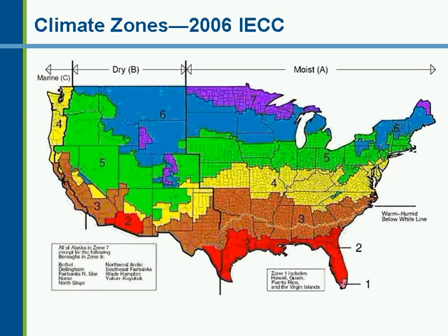That gives you a theoretical total of 24 zones, but not all of those zones occur. If you'll notice the marine zone, nowhere is zone 1 or 2 or 7 or 8. Nowhere do those occur in the marine regime. So there are fewer than 24 zones. I believe if you look at all the actual zones that occur in the United States, and then further consider that the code itself doesn't provide unique requirements in all of those that remain, there are something like 15 unique zones in the new code.